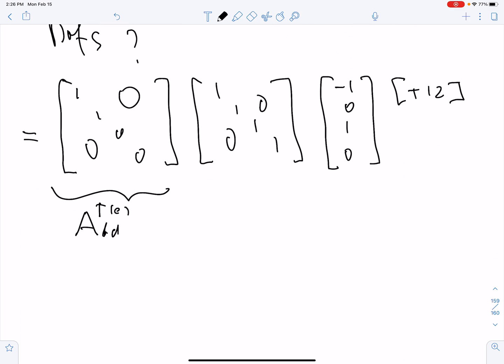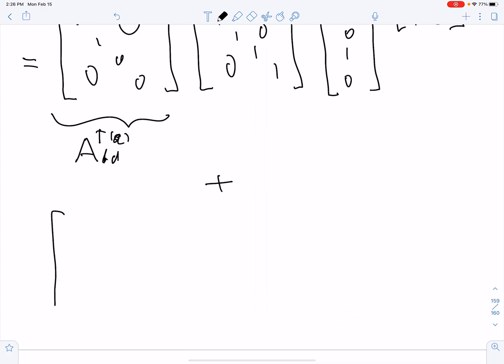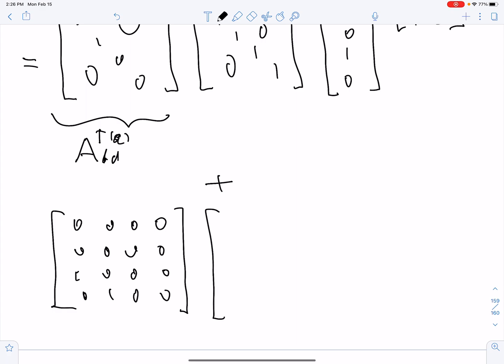Okay. So this is the contribution from element A, right? And then plus the contributions from element B, right? You need to sum them all together. If you recall from the notes, the Boolean was like this: 1, 0, 0, 0, 0, 1, 0, 0. Here you have to use the rotation: 0.8, minus 0.6, 0.6, 0.8, 0, 0, 0, 0, 0, 0, 0, 0. And you repeat,